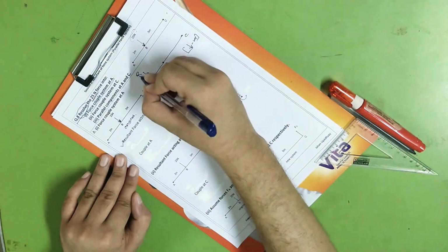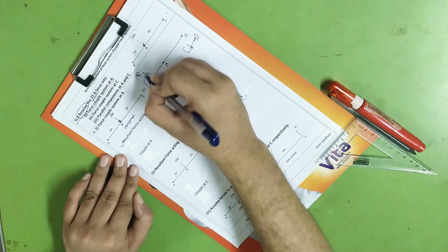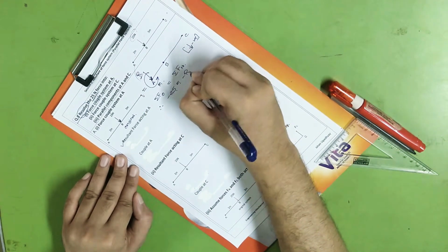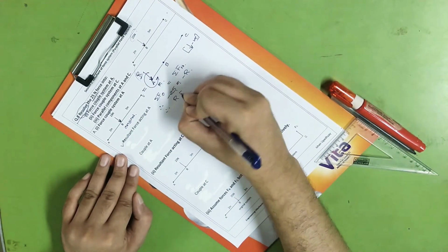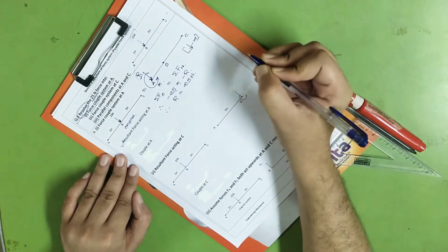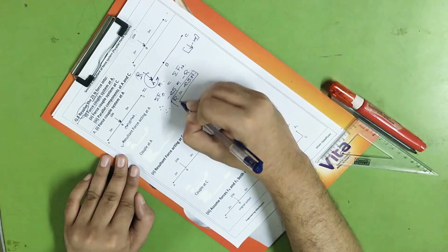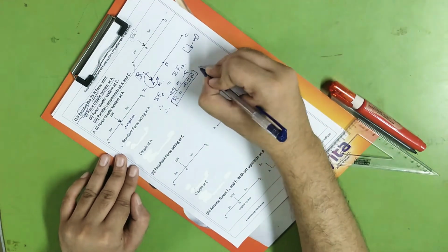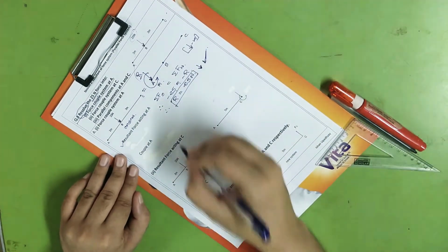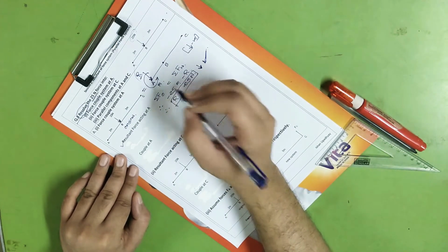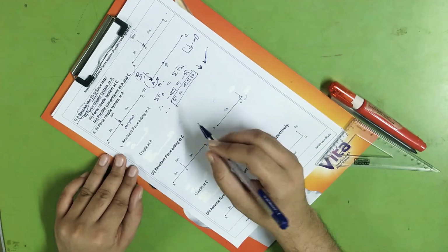Okay, and here you can see in the original system there is only one force, so 25 is equal to, in the new system there is again one force, that is R. So I'll say minus R, because I have assumed that R is acting in the downward direction. With that I'll get the value of R as 25 Newton, right? And the direction I have assumed is downward. When I'm getting a positive answer, my assumption is right, and hence the 25 Newton downward force assumption is right. So out of this resultant force and a moment, I got the value of the resultant, that is equal to 25 Newton.